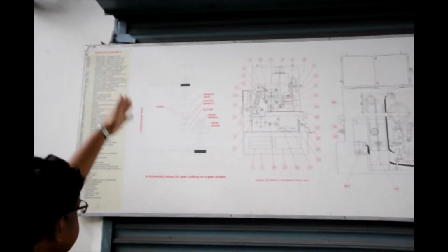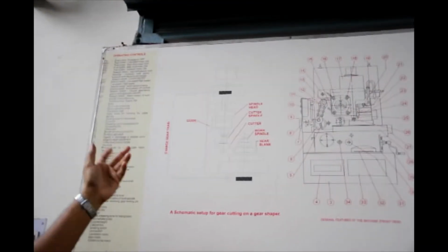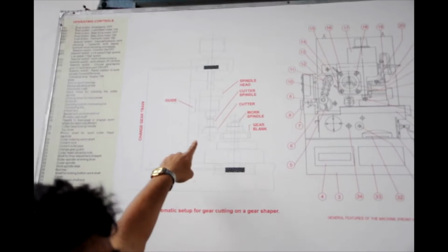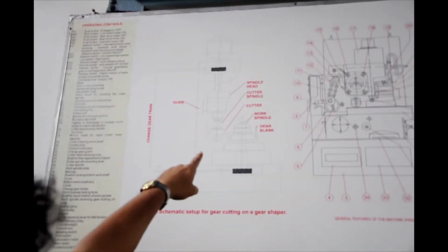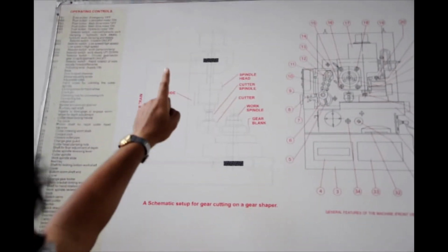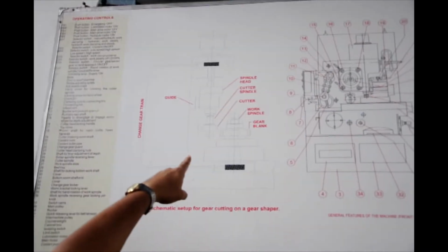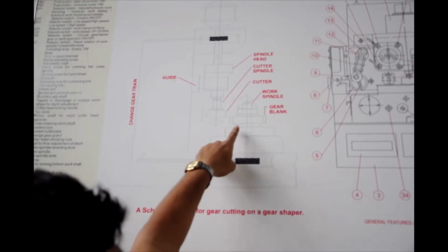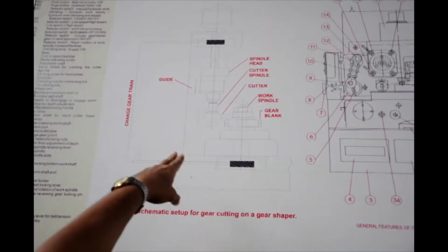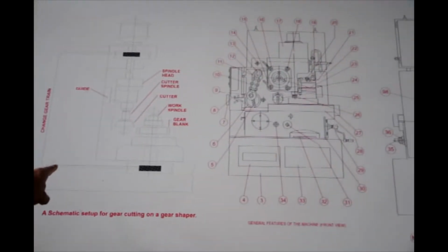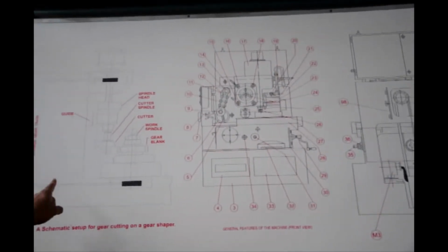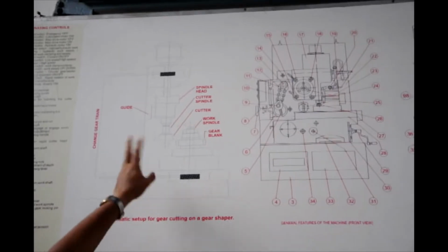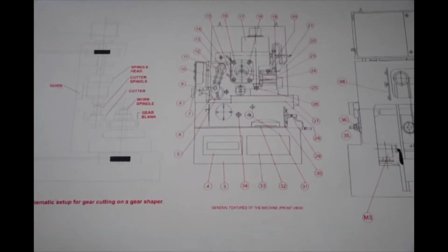It is a horizontal line, and along with that the different kinds of rotations will take place, and this is nothing but the cutter itself. The cutter is tungsten carbide, looks slightly yellowish, and tungsten carbide has very good wear resistance and all those kinds of characteristics. So it is a powder metallurgy product. This is the gear blank, and according to the gear blank, the cutter will be placed. Gear cutters and other things I have already told you, depending on the fixed module and fixed helix angle that will be set, and on the basis of that these cutting actions will take place.